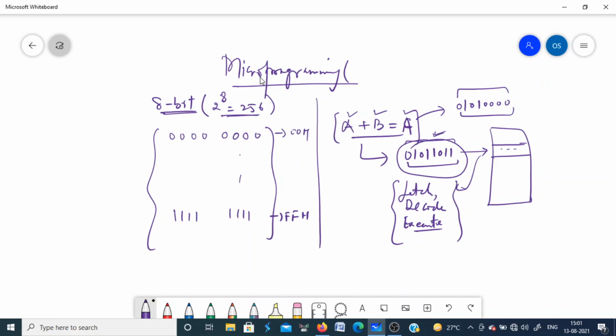This is the overview of what machine code is, and how the processor fetches, decodes, and executes these instructions. So the machine code is very important. For each instruction, you have a particular bit pattern, which is called the machine code. Once the processor gets this code from the memory, it decodes it, and by decoding we mean that the processor comes to know that it has to perform this operation. How that operation is performed needs a logic circuit, which is already in the ALU, so that has to be activated by using some clock signals.